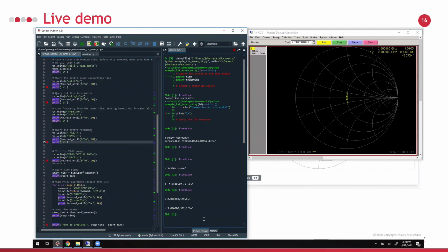Next, we'll be controlling the VSWR of 20:1. The software allows a few different ways to do this. I can either set up a gamma in terms of magnitude and phase, I can set up a VSWR starting point in mag and phase, or I can run a VSWR circle for max speed in either a step-by-step or a continuous mode. In this demo, we'll be